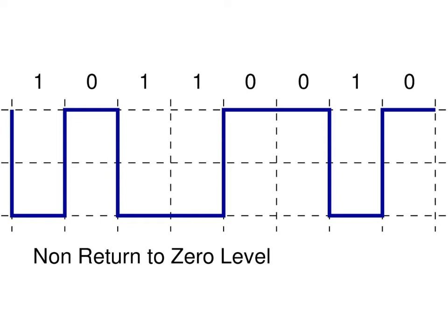So this is one of the simplest schemes that we'll see for mapping digital data to digital signals. We transmit a pulse for some predetermined duration, this time period, at some level to represent the bit that we're trying to send. And note that non-return to 0, if we give these voltage levels, this is 0 volts in the middle.